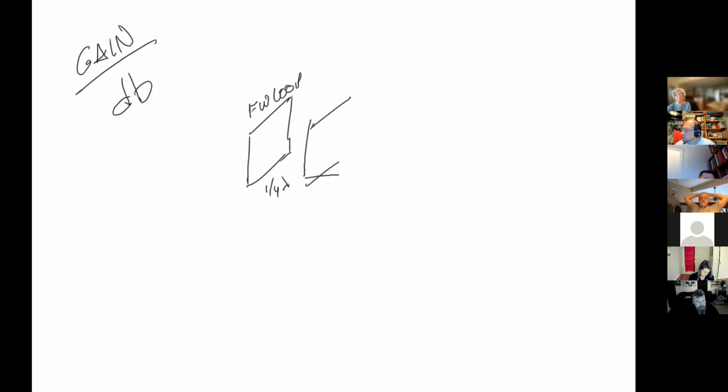Okay, so a beam antenna is an antenna that concentrates a signal in one particular direction. So we can draw a couple of different ones. One is called a quad. So this is actually a full wave loop right here. So this is actually a quarter wave on a side, and this is called a loop. This is a full wave loop. A quad is actually two full wave loops, where one of them is driven energy, and the other one is parasitic, as it's called.